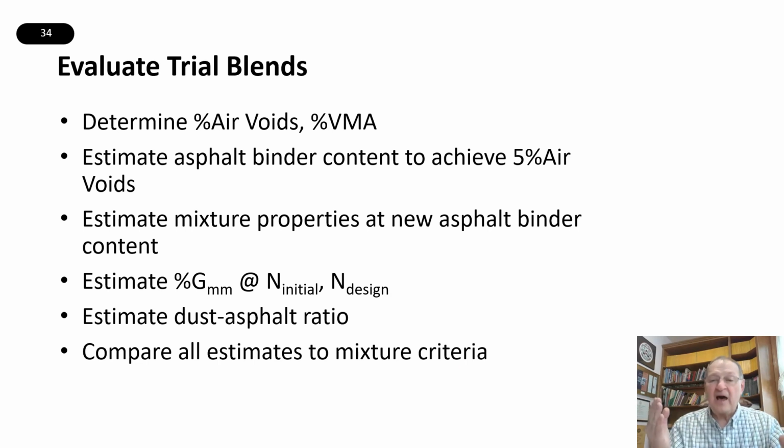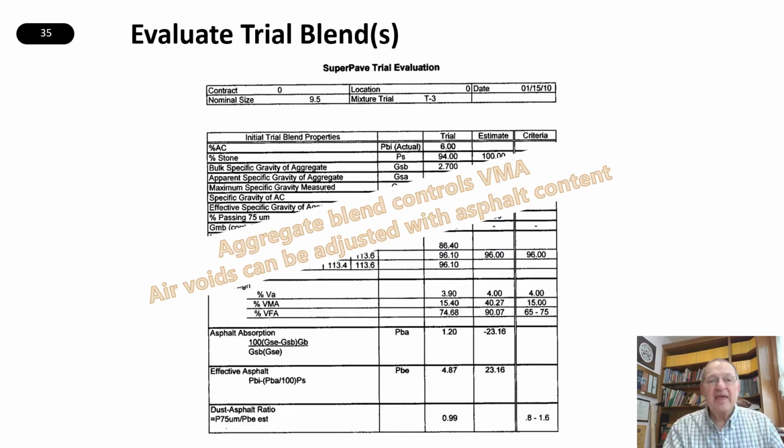So this is how we are going to evaluate which, if any, of these 3 trial blends will provide a suitable mix design for us. So the aggregate, the thing to remember is that the blend of aggregates and the way they pack together is going to control the VMA, and the air voids are adjusted with the asphalt content.